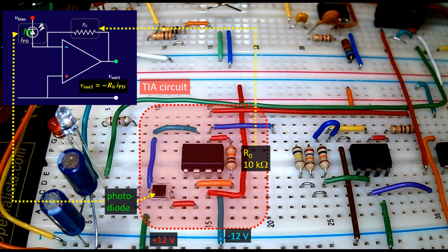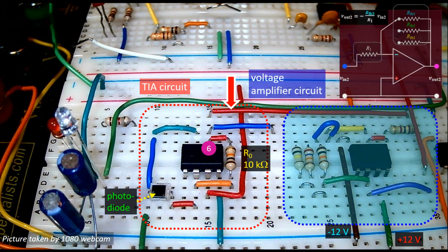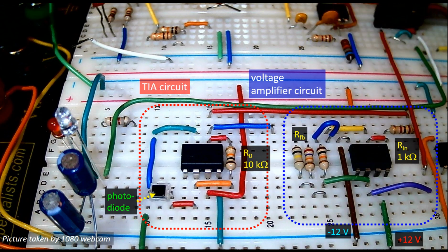Note that the photodiode is reverse biased, that is, its cathode on the left-hand side is connected to plus 12 volt, and its anode on the right-hand side is connected to pin 2, which is the inverting terminal of the op-amp. The output of the transimpedance amplifier, pin 6, is connected via a red wire to the input terminal of the voltage amplifier that is discussed in Part A, Lab 4, shown here in the bluish enclosure. The input resistor Rin is 1 kΩ, and the 3 feedback resistors can be selected with a blue loop jumper wire for different gains. The optical receiver circuit is connected to the AD2 for measurements.